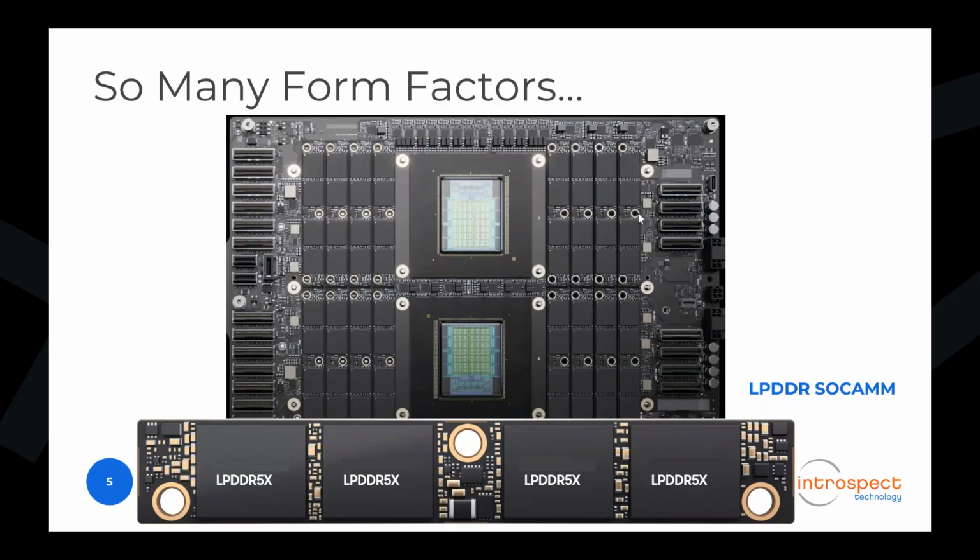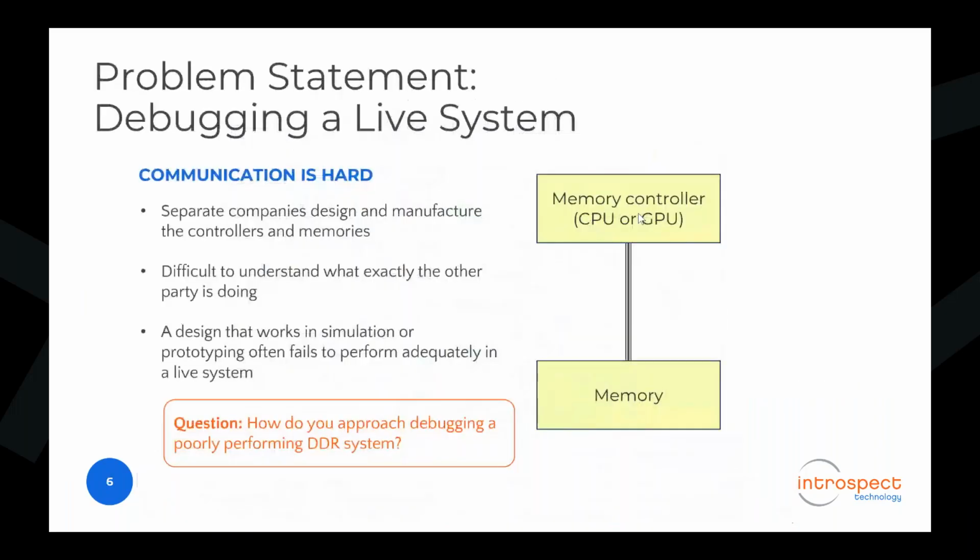And so we're here to talk about debugging these applications and how to actually make sure systems work, and where the problems come from. As we state here, the problem statement is the more memories you have on a single board, the more interoperability challenges that you will face. And the interoperability challenges are basically associated with communications challenges, right? So different interpretations of the same specification, or simply bugs in implementing the command sequences and the write and read sequences into the memory. So it's very difficult with a black box approach to understand where memory failures would occur,